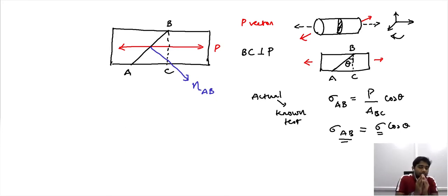So that is the primary reason why we considered the cross-sectional area in the first place. When we talked about the test tensile loading condition, the reason why we focused on the cross-sectional area that is perpendicular to the loading direction is because it is possible for us to understand the resistance offered by the material along this particular area.